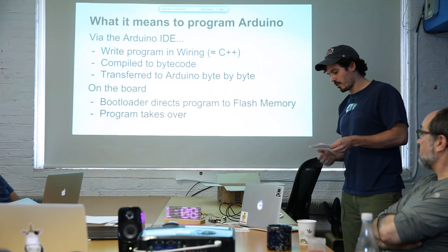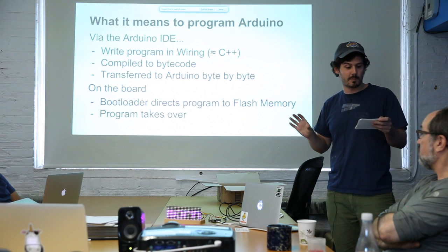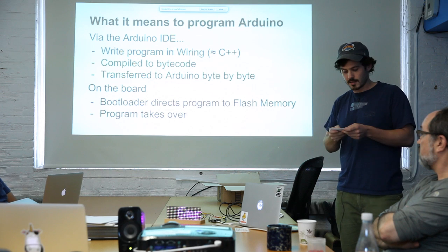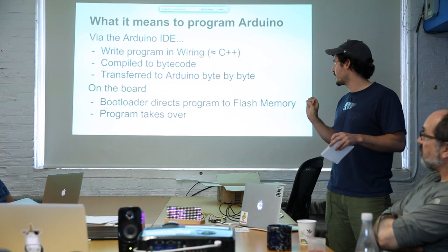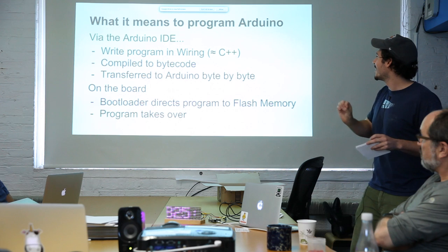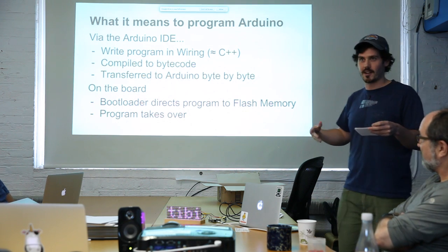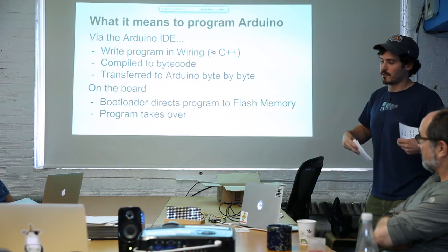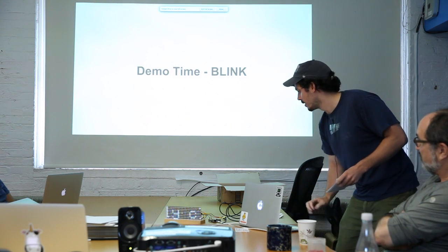Okay, so what it means to program Arduino. You're writing Wiring, which is, I think, almost exactly like C++, with some simplified syntax and some built-in libraries. You are then compiling to bytecode, transferring your code to the Arduino byte by byte. And on board, there's a bootloader that is, I think this is what a bootloader does, directing the program to the flash memory, and then letting the program take over. And once the program is on the Arduino, if you power the Arduino, that program will run. It's there.